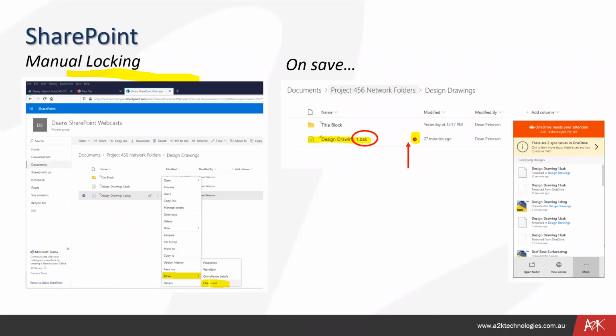These checkouts and check back ins are not going to work very well with the way AutoCAD and Civil 3D drawings work. And in fact, that's what this is talking about. There's your adding the backup file, and these two sync issues relate to the DWL and DWL2 files that it couldn't sync because they're not recorded. Okay, so there are issues around this that you need to be aware of.